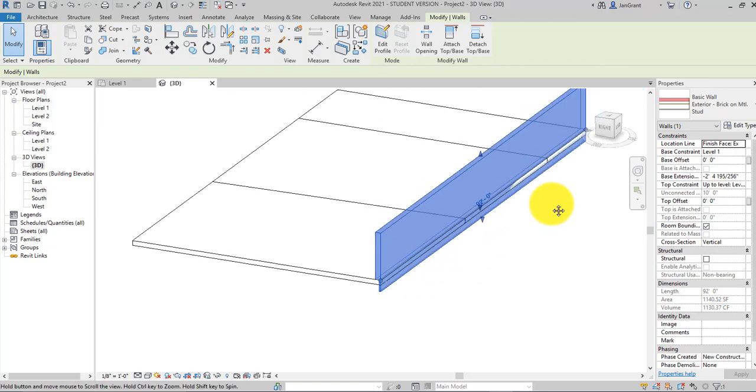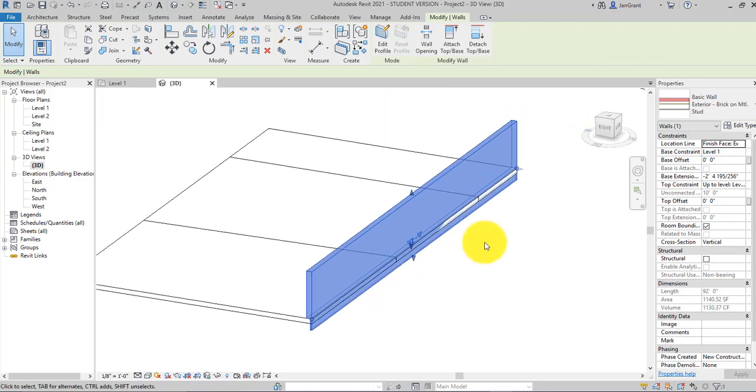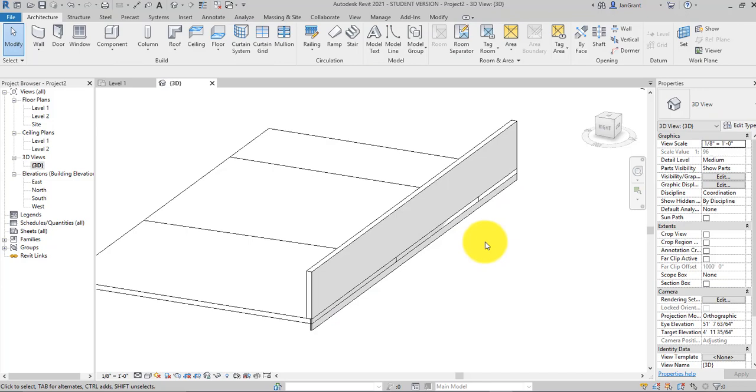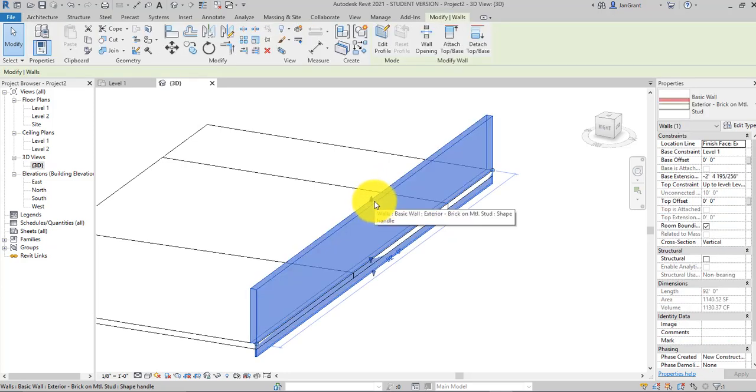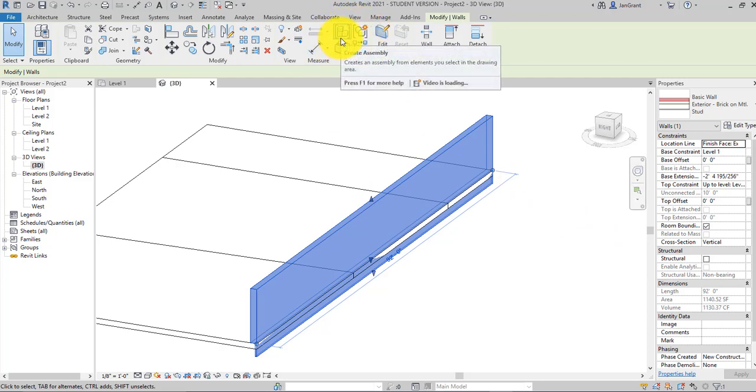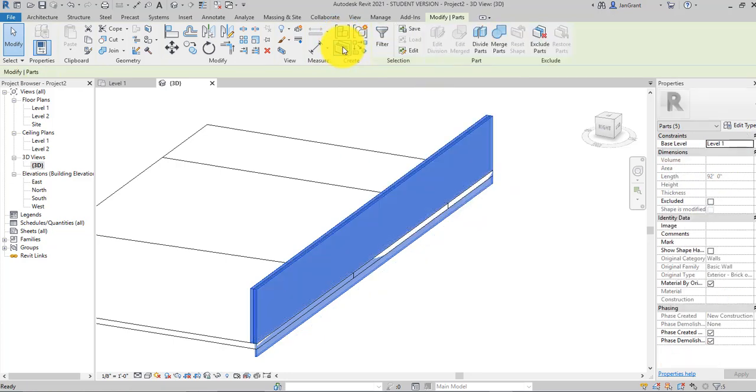Okay, just wanted to show you several different tools in this video so that you're not creating an entire project, but as a construction manager, you would know how to use the software. We can select here this wall and go to the Create panel and pick Create Parts.